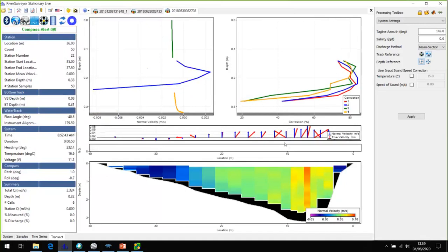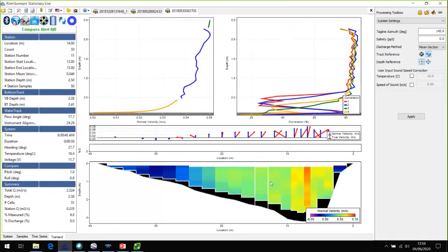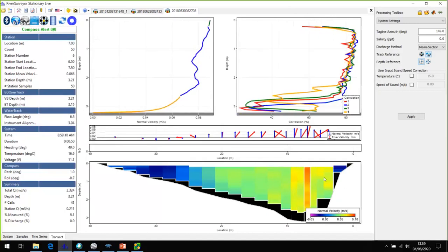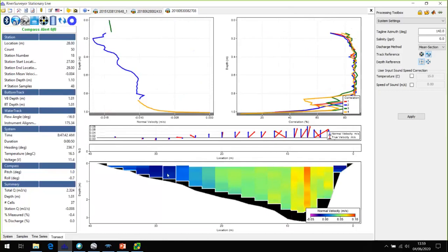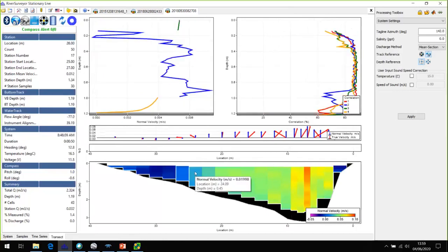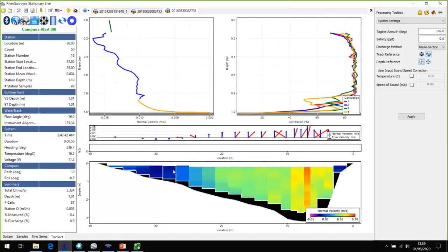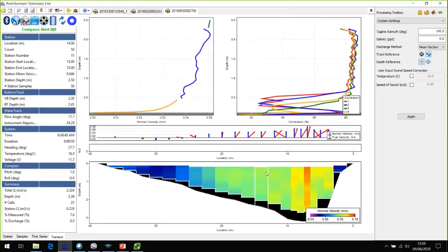And you can see my problems. I've got flow down here with really meandering, slow profiles. It's only going up to 10 centimeters a second, and back here I've got negative flow. The flow's not behaving itself. So the best thing to do is to go stationary and try and average this rather than completely busting 8 transects and spending hours. So yeah, really good for low flows.